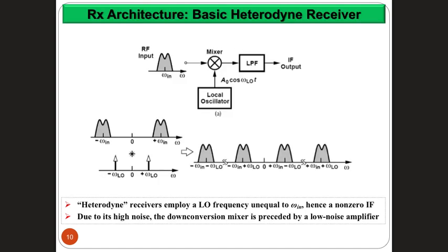So after taking those considerations into account, the filtering considerations for narrowband transmission, we end up practically using multiple stages of filtering. We have the band selection filter, we have the channel selection filter, and there are practical considerations for each one of them: when it should be done, how it should be done, in order to achieve practicality and efficiency at the same time.